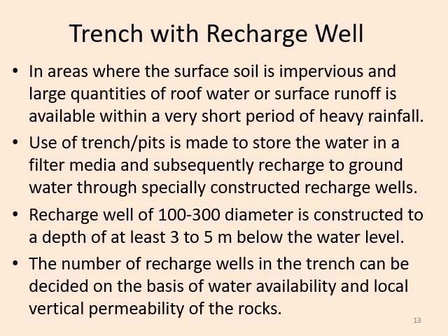A recharge well of 100 to 300 millimeter diameter is constructed to a depth of at least 3 to 5 meter below the groundwater level. So it will go deep down, at least an extra 3 to 5 meter below the groundwater level.